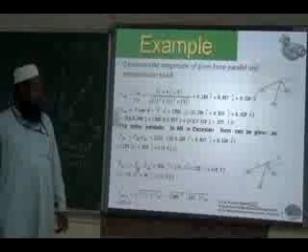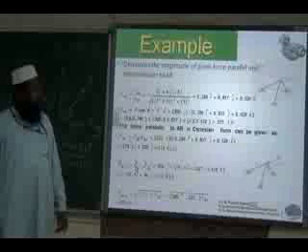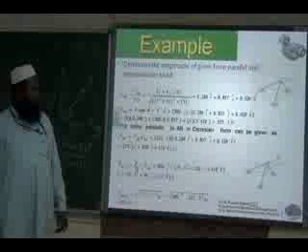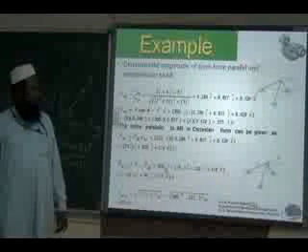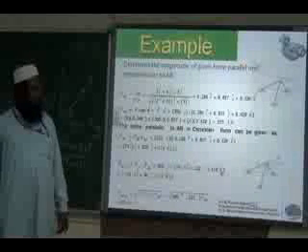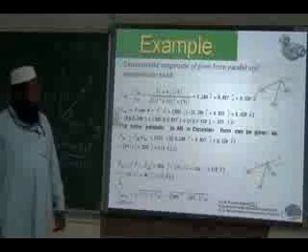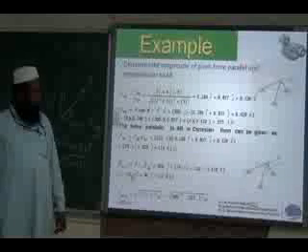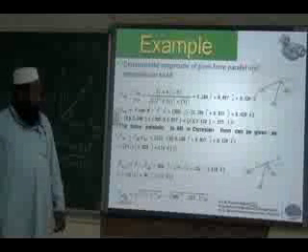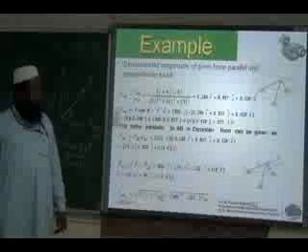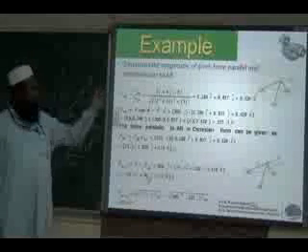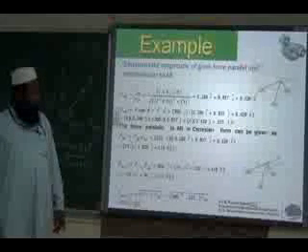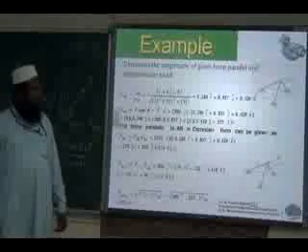So we subtract FAB parallel from the given force vector: 300j minus FAB will be our FAB perpendicular component. To find its magnitude, we use the Pythagoras theorem, or we can find theta and get it the other way.